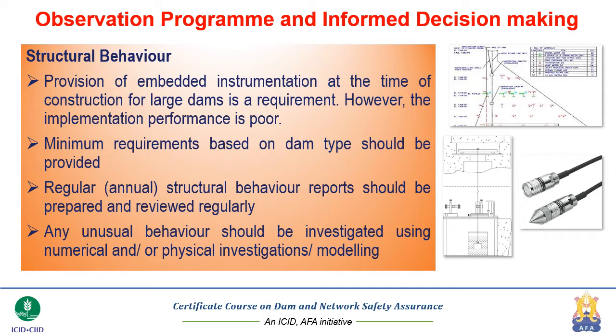Likewise, the pore pressures in an earth and rockfill dam, the seepage discharges at the downstream toe and through the relief wells, and various other conditions of slushy ground, etc. on the downstream, the profile of the slope, the settlement of the surface of the earth dams or rockfill dams. These are the minimum requirements which have to be ensured every time we operate a dam.